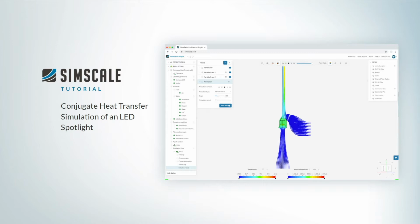In this video tutorial, we will perform a conjugate heat transfer simulation of an LED spotlight. The objective of the simulation will be to understand how natural convection helps in controlling the temperatures developed on chips inside an LED spotlight. This is because a poor LED design with high temperatures can be harmful to the lifetime of an LED package.